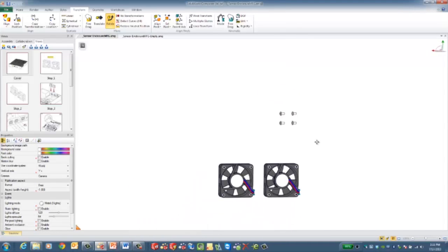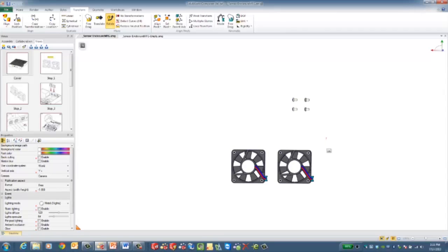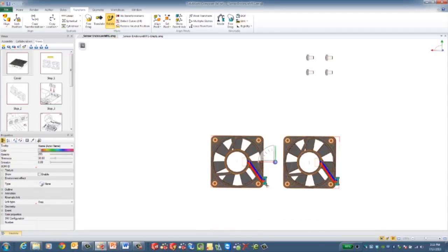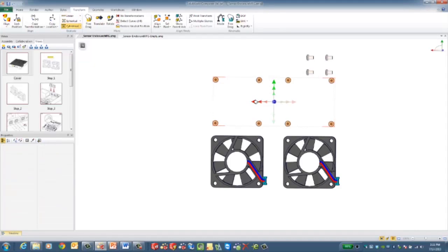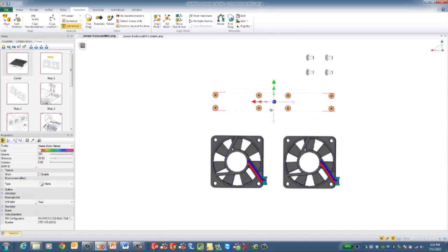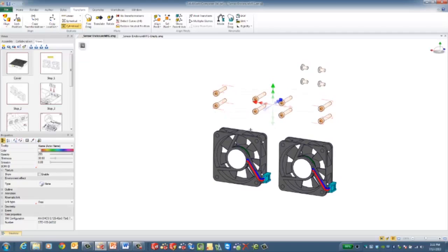So that's pretty cool. But what about these ones? I also want to show the screws that are going to be used to install the fan. Again, it's all about quickly being able to select and manipulate geometry. So I'll take all these bolts and move them up. I want to bring them close together. Another good place to use my Cylindrical Explode tool, to easily move everything close together, and then now I want to rotate them. Well, what happens if I grab all this stuff and rotate it? That's not necessarily what I want.